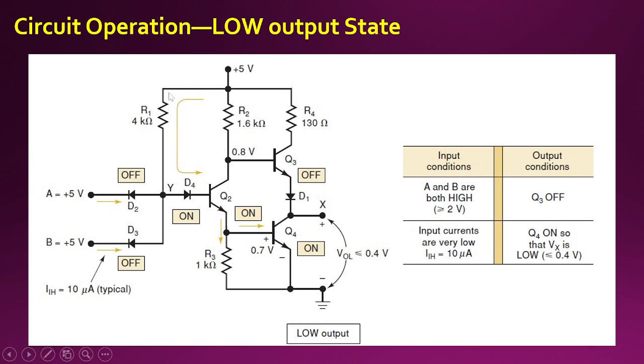But have a look at the diode D4. The P type is biased to +5, the other side is at lower potential, hence this particular diode will conduct, and a base current is expected to enter this particular transistor, which will switch on the transistor, and we will see a collector current flowing from collector to emitter through this particular path.